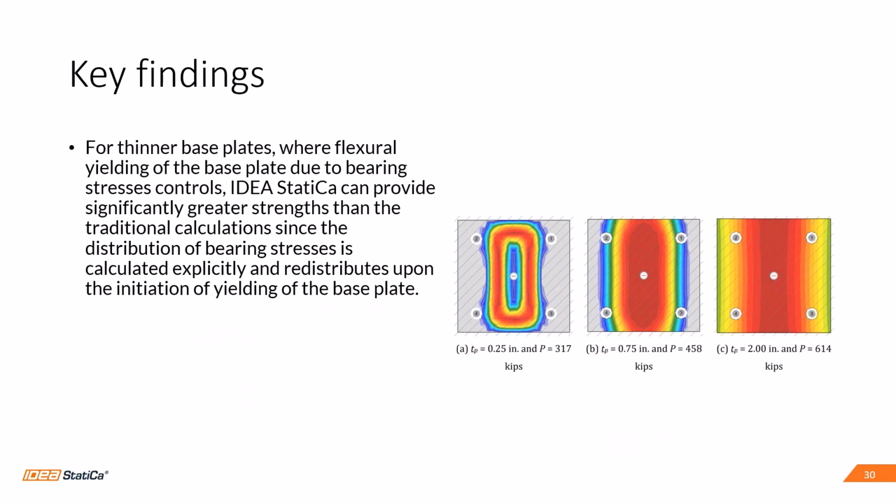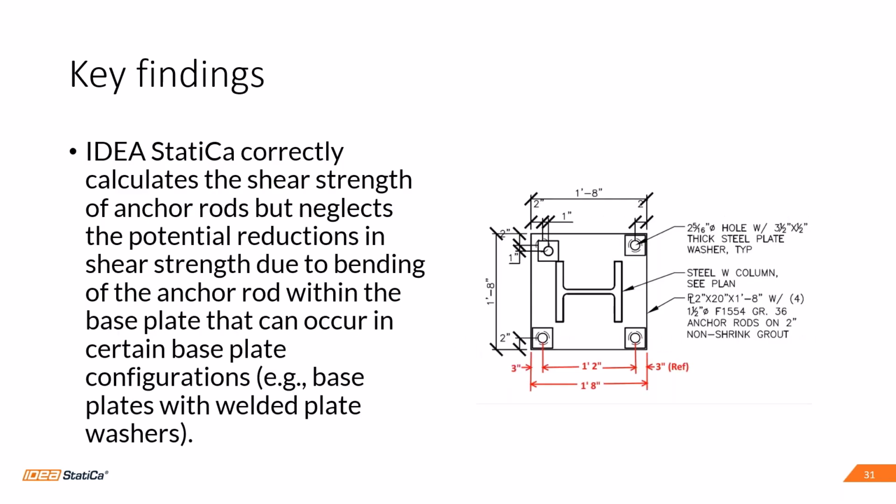For thinner base plates, as I said, results from the traditional calculations and IDEA StatiCa differ significantly, because again, we are getting the real stiffness of the base plate. All right. So that's why we have different results over there.